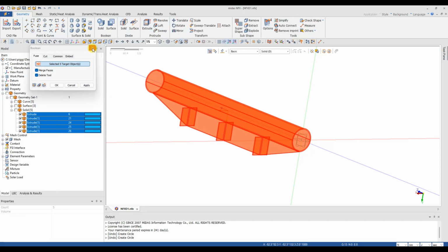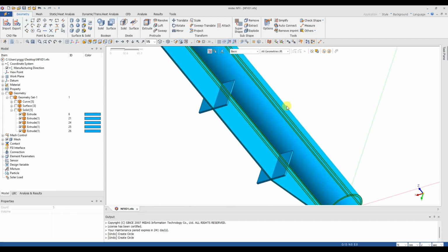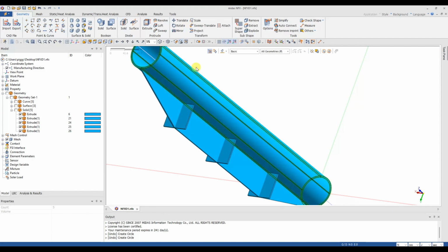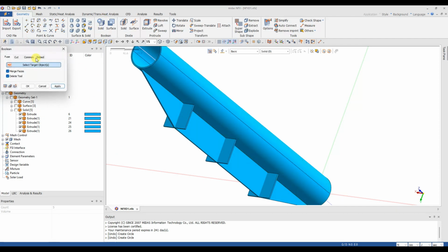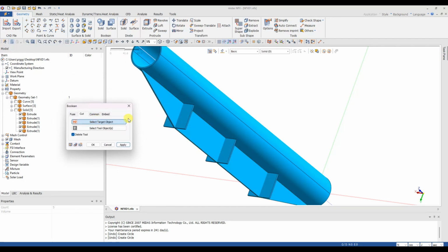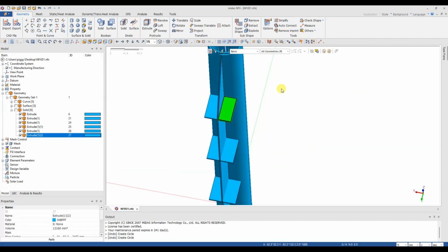So if you would like to determine the contact, all right, since this is overlapping, it's not supposed to be in this way. Before I do the contact, I need to make a cut. I make sure that this is cut from the tools, right, without deleting the tools, and apply. And this is how it is supposed to look, right? So one part here, another part here.